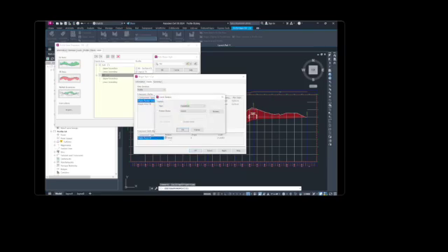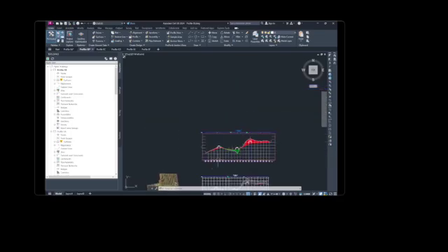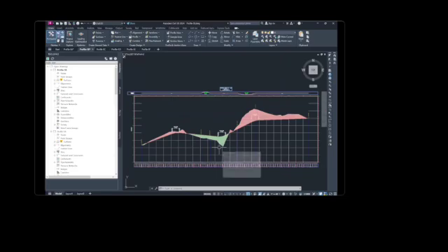And then in the shape area fill, in the pattern, click the dash, and then in the pattern name, change it to cross, click OK, and in information, change it to fill. The profile view properties dialog box closes and the new hatch pattern is displayed in the fill areas between the profiles.